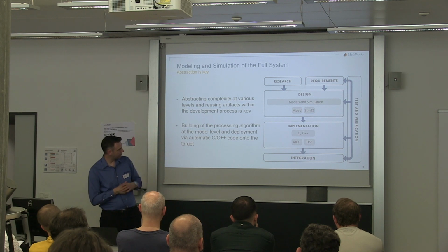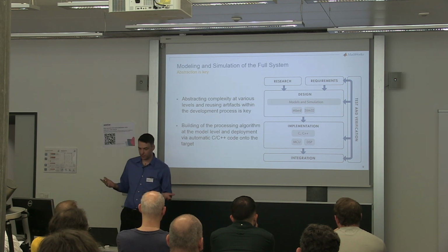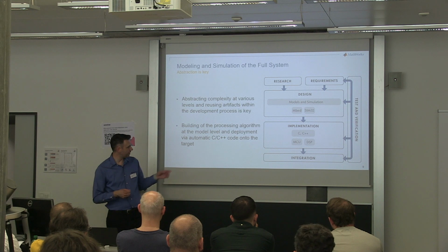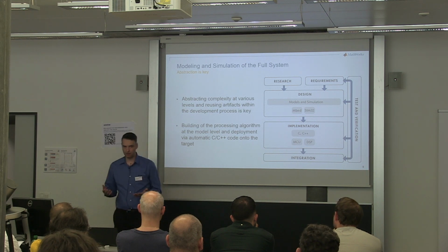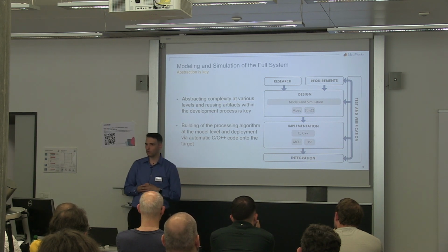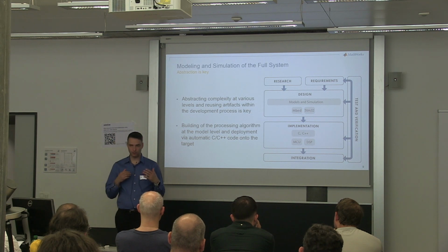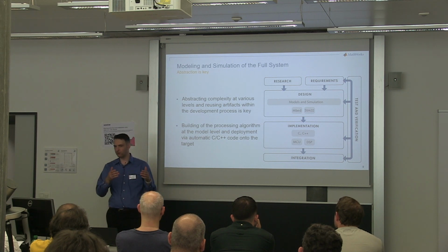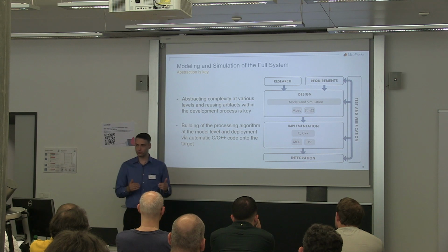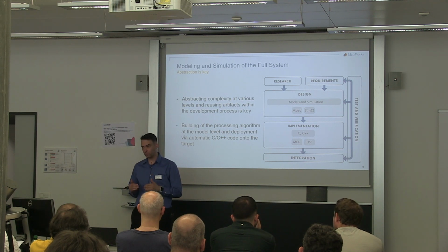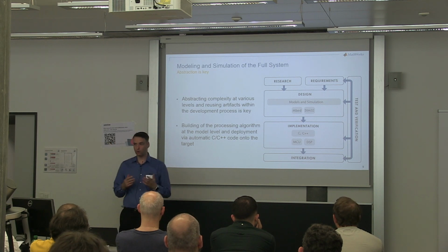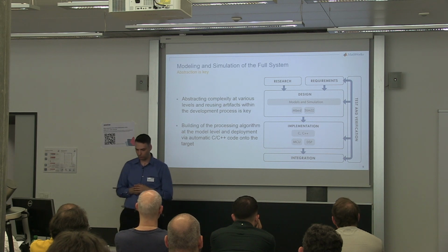And then the third phase is the implementation phase, out of which we will generate C code, in this case, either for a microprocessor or for a DSP. And finally, we have the integration phase, where we will connect to third-party tools, like, for example, the compiler, in order to generate the binaries, but also to reuse code replacement libraries. Because when we talk about code generation, for example, if I have an IIR filter, I do not especially want to generate C code directly from the implementation itself, but reuse subroutines that are already optimized for the processor I would like to use. So this is what is called code replacement libraries, and this is available at the integration phase with the hardware support package for the specific target you would like to program.